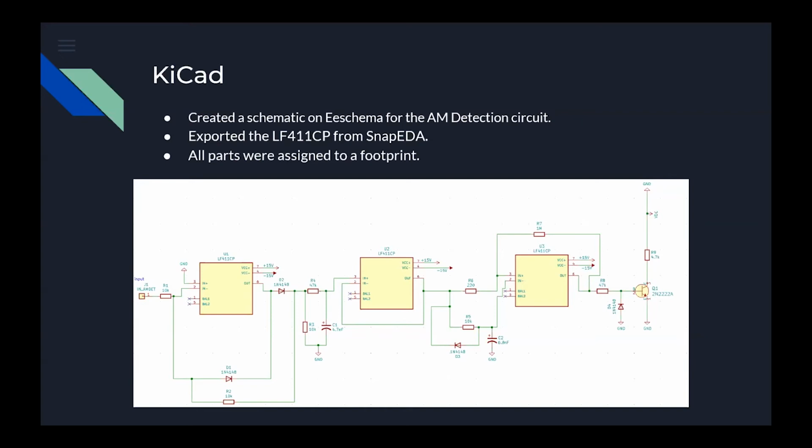For the LF411CP op-amp that you see, we have exported its symbol and footprint from SnapEDA, since KiCad's library does not include that specific op-amp. Next slide.